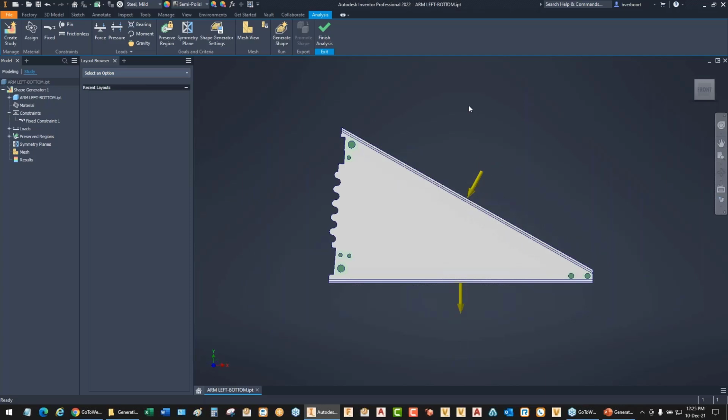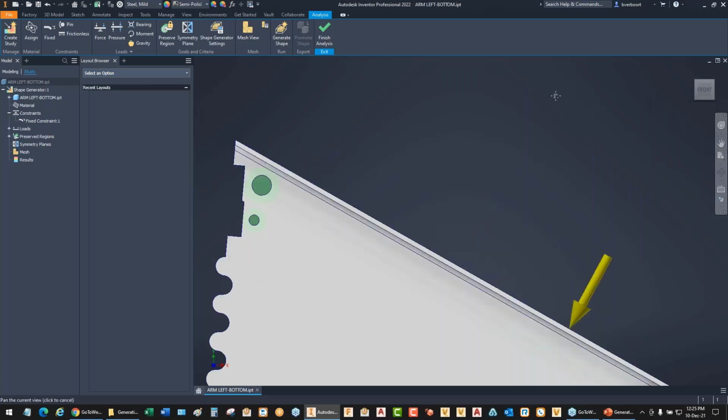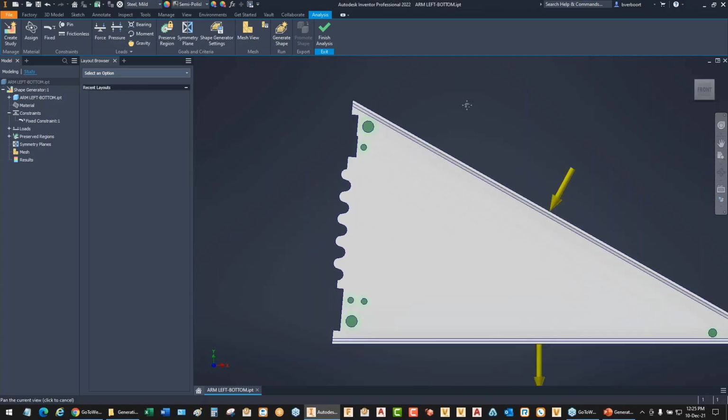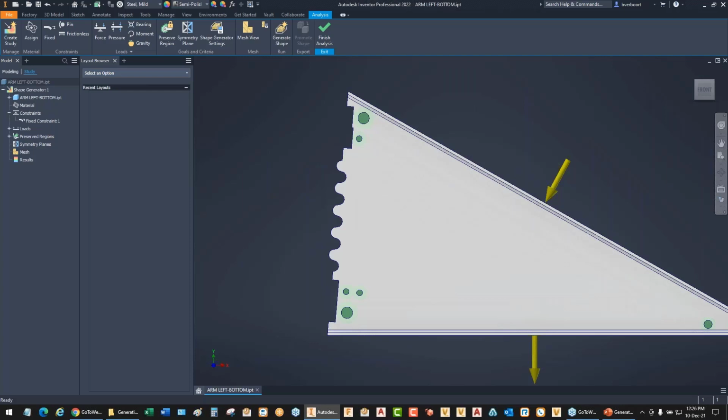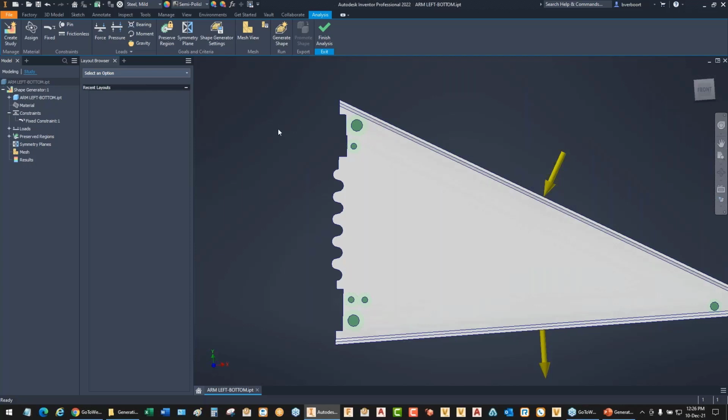is, first step is make things a little bit easier for me to select. I'm going to go ahead and rotate. Use the standard Inventor commands for rotation, and our old friend function F4. And I'm just going to rotate that around a little bit so that I'm not so quite askew with the features that are on that face that angle. And then that's going to help me, because when I get ready to preserve additional regions, I'll be able to window select that a little bit easier.